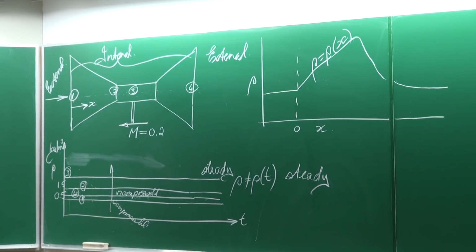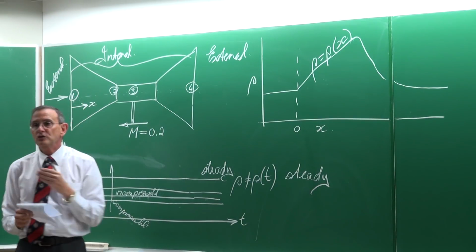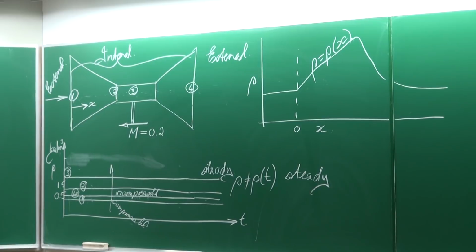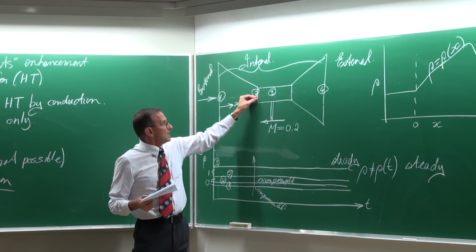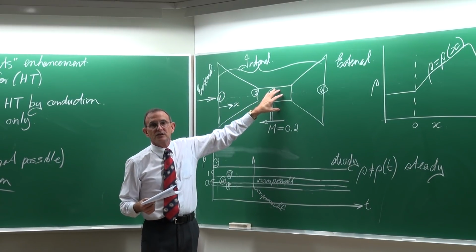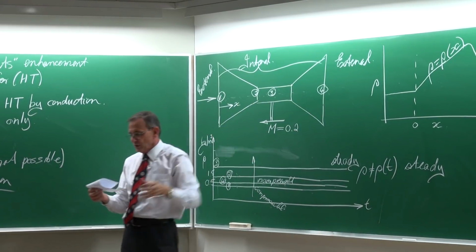So we cannot consider that as incompressible flow. It is compressible. So it all depends where you're measuring. If you are sitting here at the inlet and you measure the density all the time, it's going to stay the same. And therefore you're going to report back it's incompressible flow. However, if you're a molecule going right through, then you will experience the process of not being compressed, then being compressed, lots of heat transfer, it's going to be heated up, and then you're going to expand through the turbine.